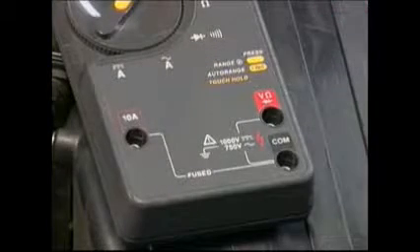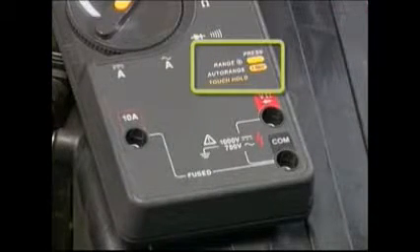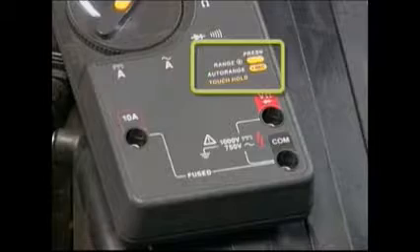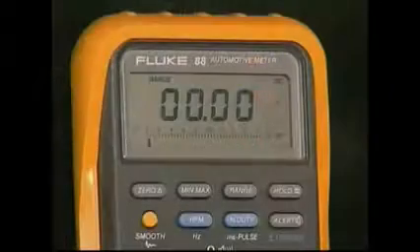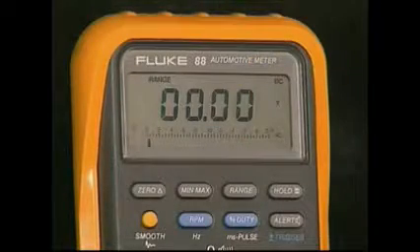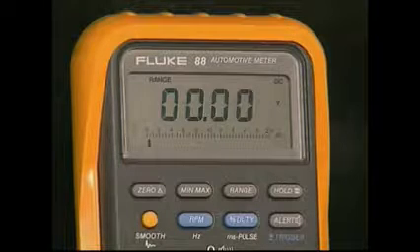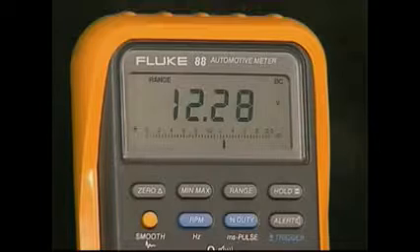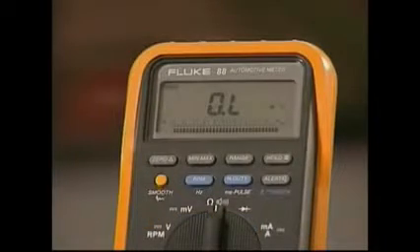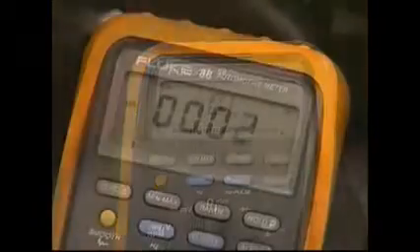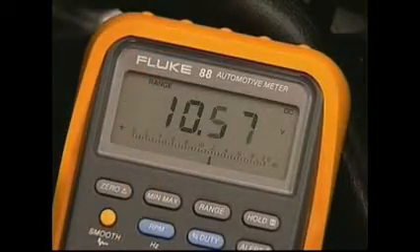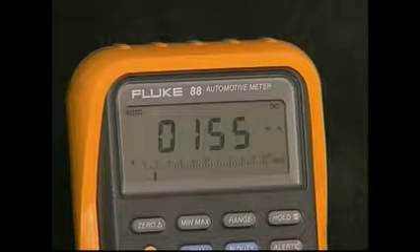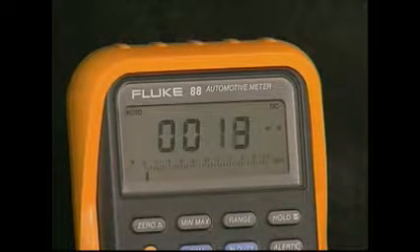Some digital multimeters will require that you either select a range for the data display or some auto-select the range for you. On manual range meters, the range that is selected determines the highest value that the meter will display. If a voltage over the manual set range is measured, the meter will read OL for over limit. To read that voltage, you will need to change the range of the meter. Auto range meters will automatically select the range of the meter to accommodate the measured values.